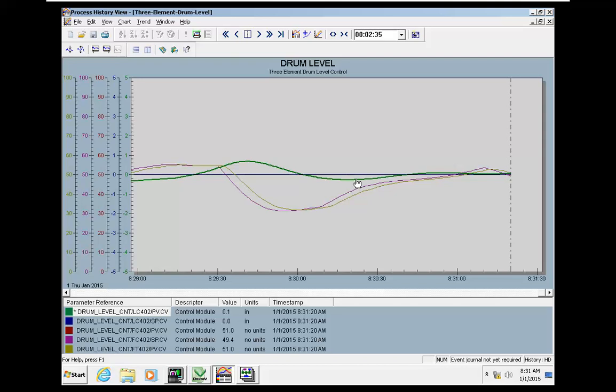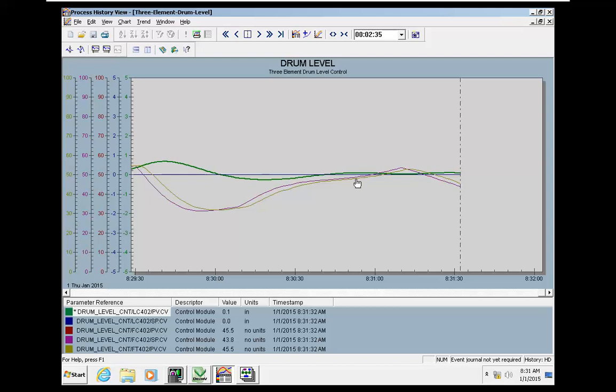It's also possible to use MPC for dynamic load changes, but for this application the easiest way is using the steam flow as the input for a feed forward.